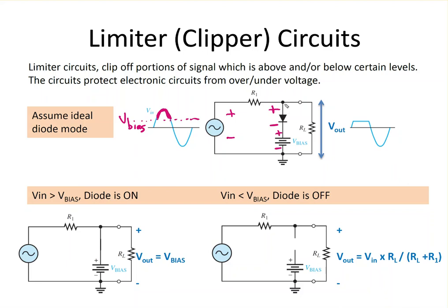Now, when the diode is forward biased, and this is what's going on in this bottom diagram here, in analyzing these circuits, they're assuming the drop on the diode when it's forward biased is actually 0 instead of the 0.7. Now, you could assume it's 0.7 if you wanted to, but the initial analysis is a little bit easier if you just assume it's 0.